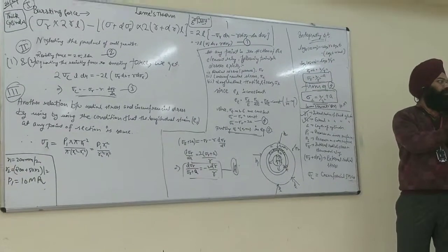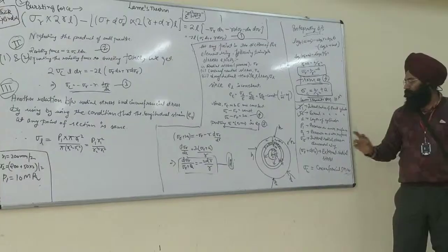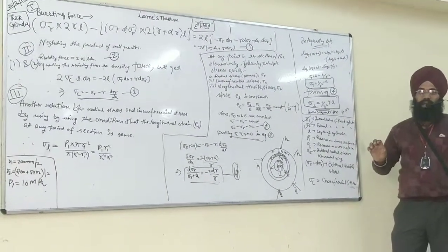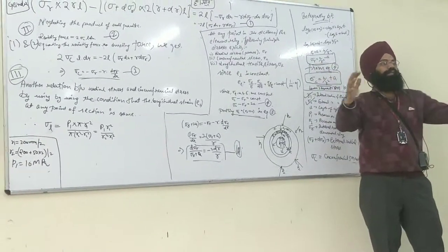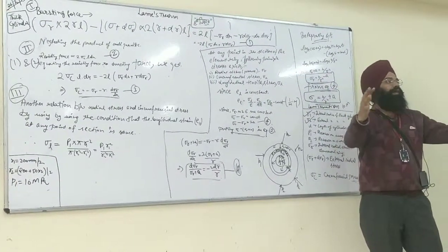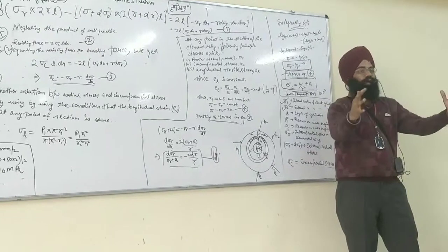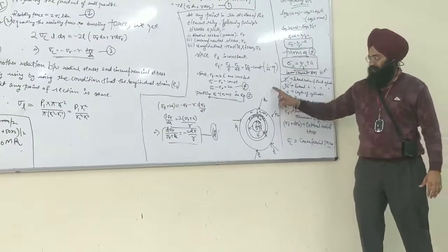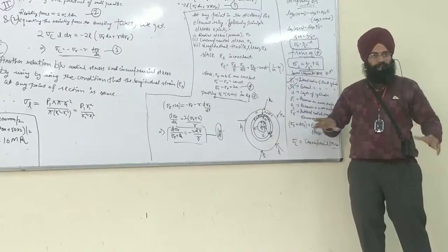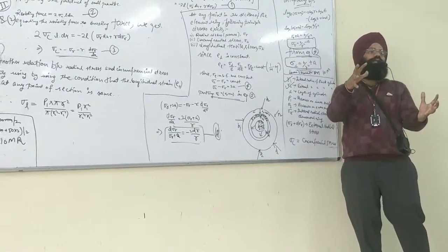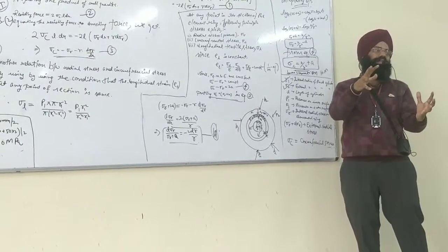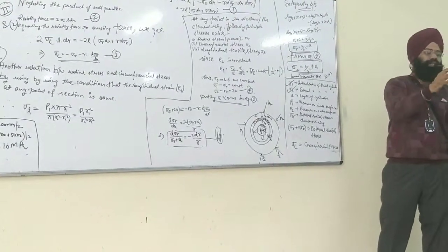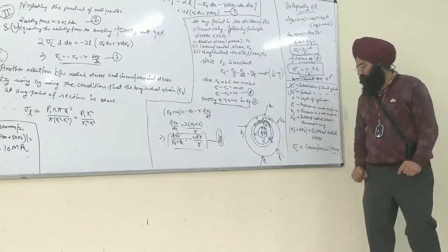The pressure of the fluid is defined as P1, the pressure on the inner surface. There will be a resisting force from the outside of the thick shell due to the wall, called the pressure on the outer surface. This is P2, because the internal pressure tends to burst the thick shell, and the outside will compress the thick shell. So that will be the P2 force.